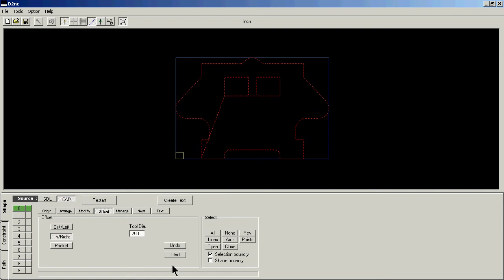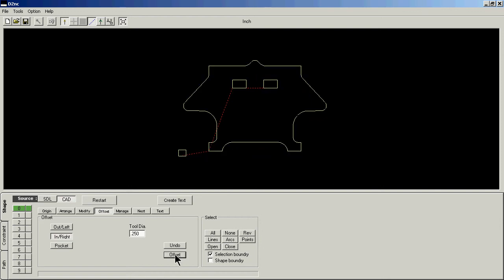This is the way the screen looked in video 15. I was having troubles, and I was jumping around here and wasn't thinking. If you look, that means that the tool offset is on the inside of the line to cut out the outside of the part, and that's totally wrong. The actual part is inside of the 00. This is the center of the cutter path.